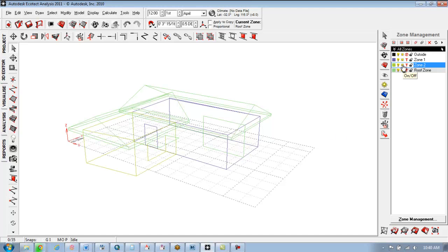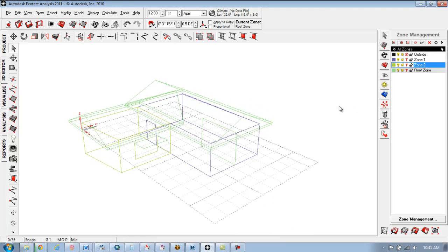And for a Revit model, when you bring it into Ecotect, you have to save it as GBXML instead of GBX. Yeah, it's .gbxml. We'll go over the import process in a second as well. But it's a standard export format out of Revit. That GBXML format is really the green building export format. So whether you're working with Design Builder or Ecotect, you're almost always going to be exporting in that format if you're trying to do some sort of environmental analysis.